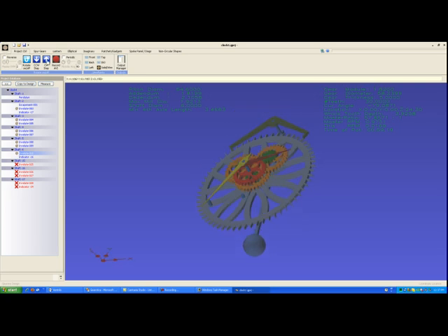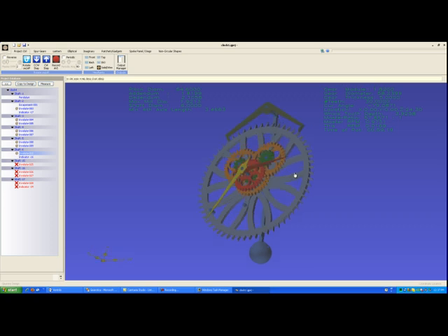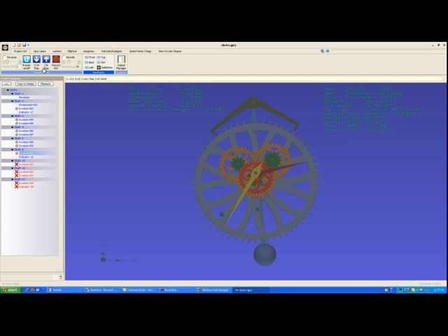What I typically do is make a round cup that misses the shaft, and I glue it to the gear, and then I put a large round flange on the indicator and have it come off of that gear. For the purposes of Gearotic Motion, we'll just show it on the shaft, because again, Gearotic Motion can't design the entire clock for you. It can just design all the important parts.